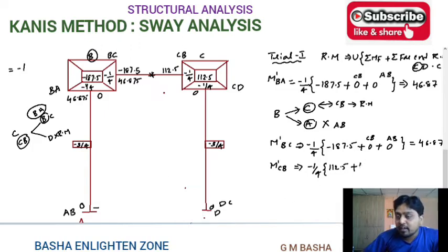So therefore I am taking 46.875, which was BC foreign rotation moment, plus the sum of the displacement contribution. So you have to look at displacement contribution in the middle. For beam it will be 0. For CB you have to look at the DC column. Okay, and if there is one more story you have to look at that one also, but there will be no first story column.